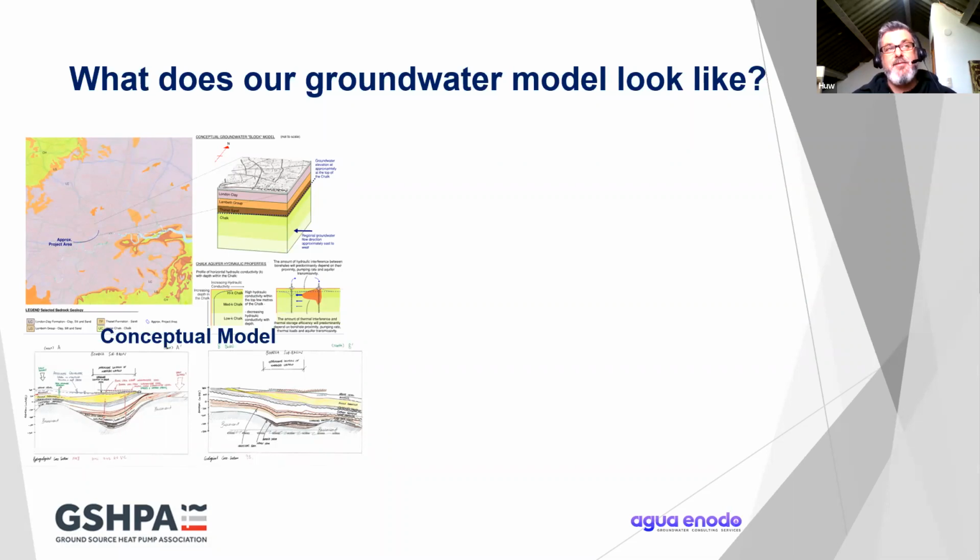At best, this is a well-characterized understanding of the controlling factors that influence the behavior of groundwater flow and heat transport in the subsurface. We construct this conceptual model typically using experience of similar geological settings and systems. Of course, we use published geological mapping, borehole records. We've touched on this in other presentations, any other relevant site reports. All these factors are considered by the modeler and used to formulate the conceptual model. This is the conceptual model that they hold in their head.